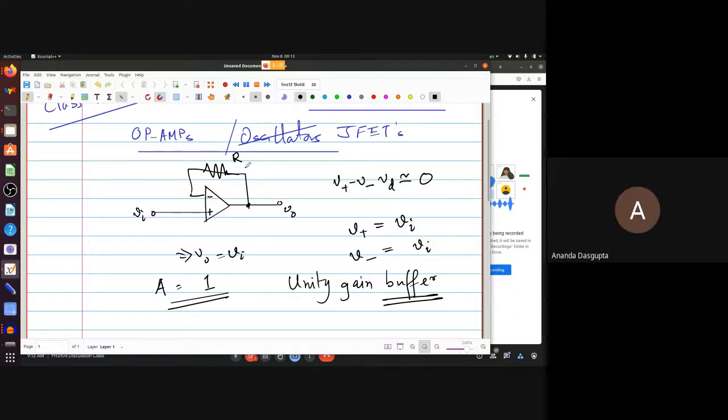No, what flows through the branch? So no current flows through the branch. Right, exactly. So at least for all practical purposes, the current flowing through this resistance R would be negligibly small, because that is the current which would be entering the negative input of the op-amp, and that's very, very tiny. Unless you go overboard and connect, say, a giga ohm order resistance there, the resistance will really have no effect.